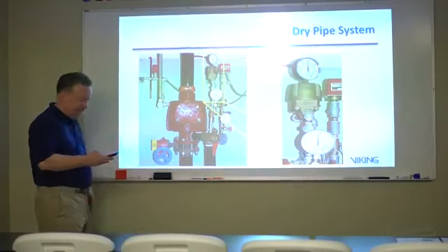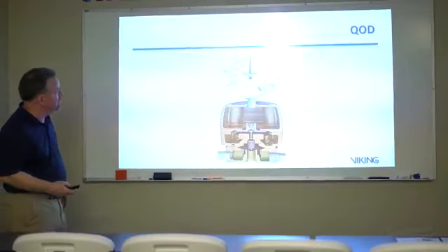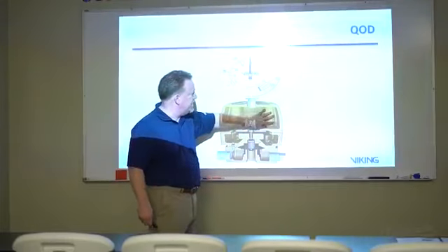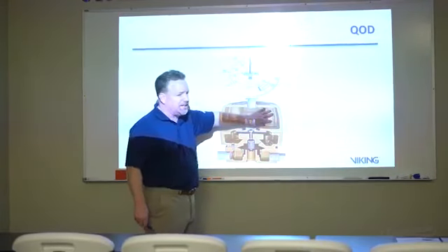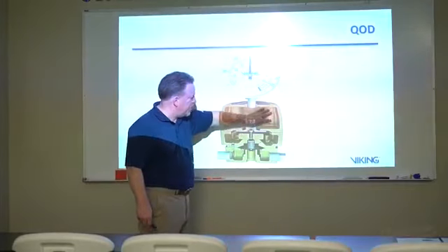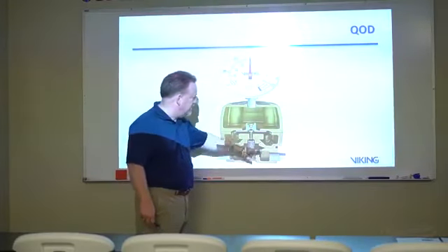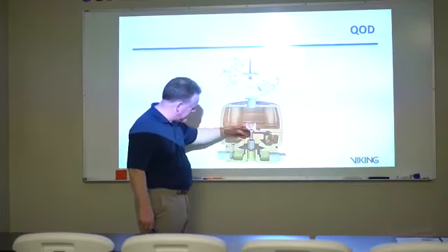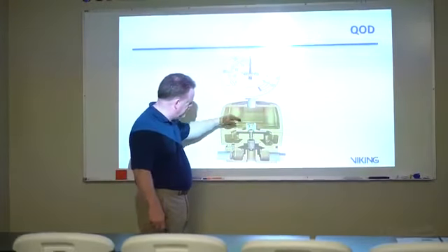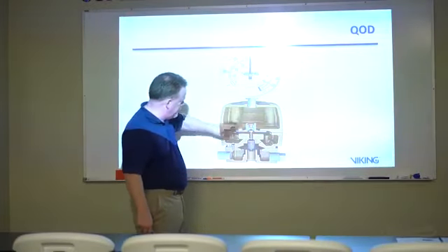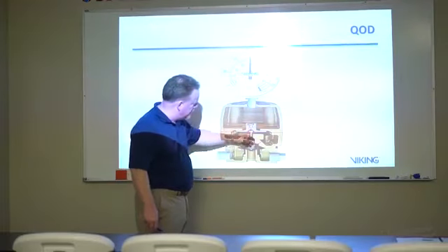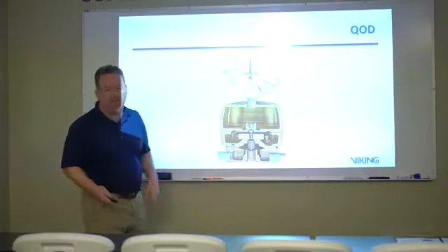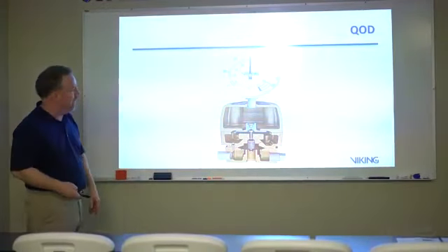I'll show you why in a second when we get to that. Here's the accelerator, the inside of the accelerator, and this particular gauge will be set at system pressure. All right, this chamber. Because what's going to happen as the system reduces pressure, this valve will operate, because this is closed off. So pressure will start to reduce here, this will push down, and the air pressure from the system will then be diverted back underneath the valve and help it operate.